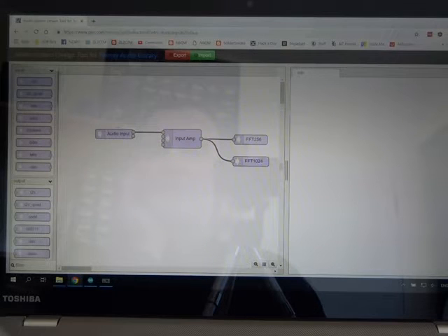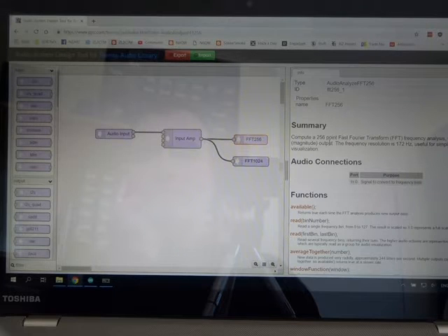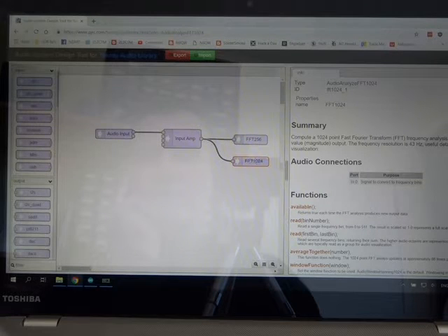Right, so at the moment what I have hooked up for testing, and what we saw on the screen there, is an audio input, which is the line in. I've got it wired through to a mixer, which I've notionally called input amplifier, and the output of that amplifier is going to, at the moment, a 256 point FFT, but I also need to have a think about, and it will be more relevant at the end of this video when we talk about how to use this for a ham band.